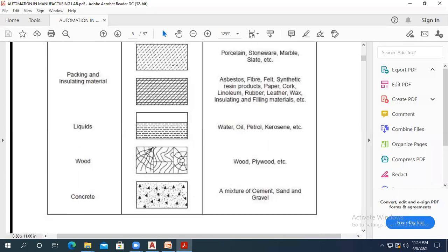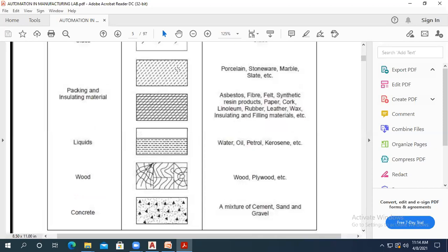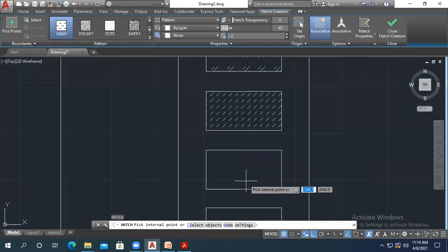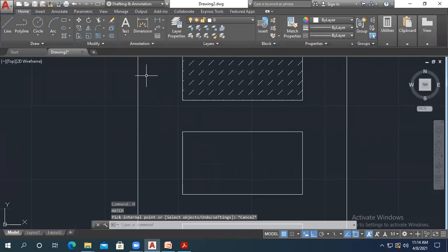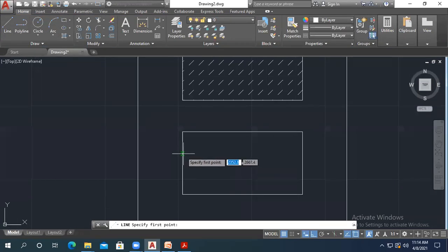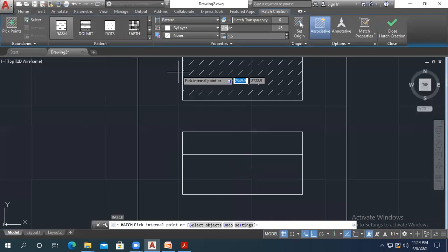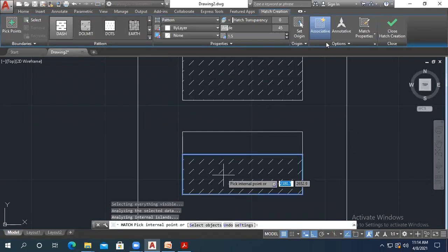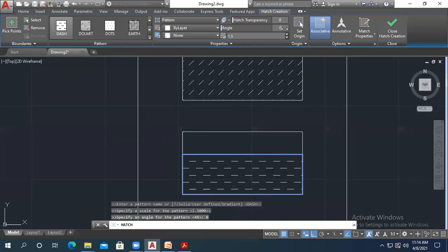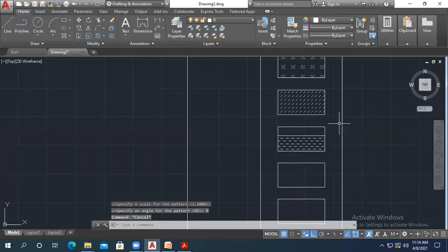This one, because we have already done a dashed one, but these were inclined. This is not inclined. And also this is partly filled because we are representing liquids. So we can split this firstly, escape. Okay, this comes out using a line. Let's see from here until here, you can hatch it. Now hatch, enter, that same dash, but not inclined, right? Like that.